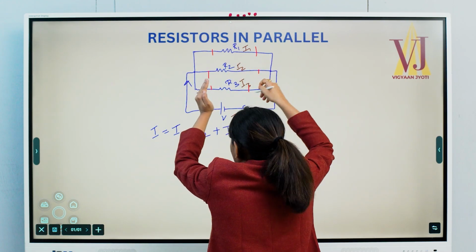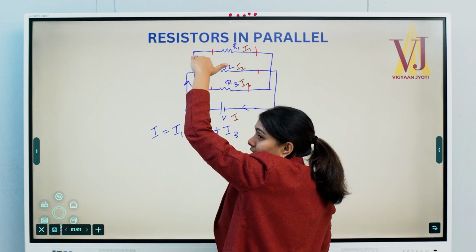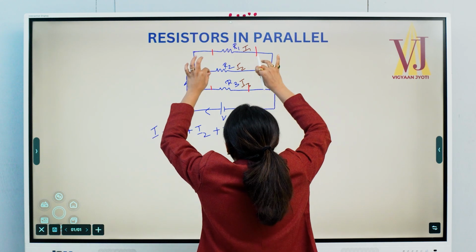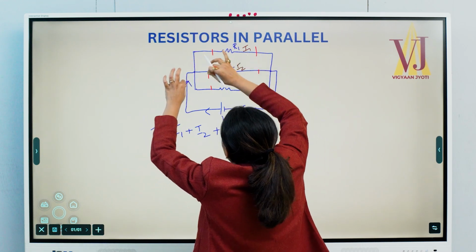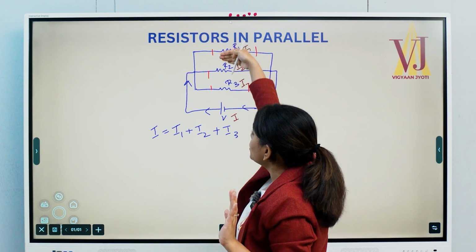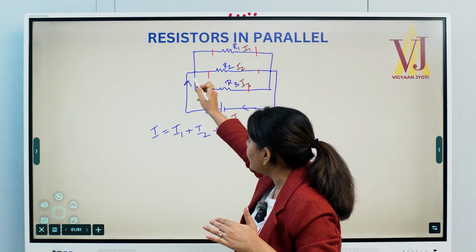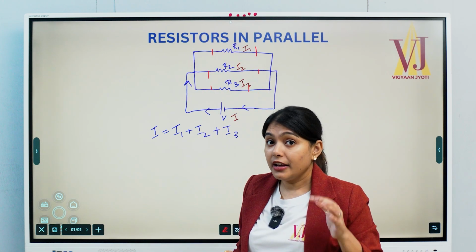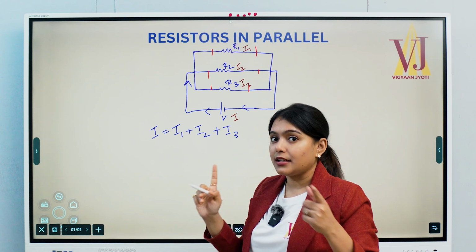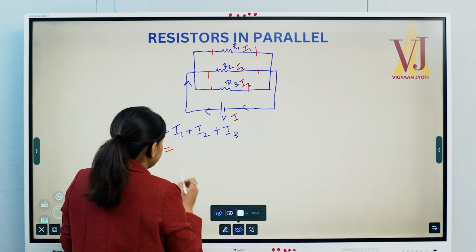All the 3 wires are having flow of current, but when we are trying to calculate the potential difference, we consider only these 2 points and see what is the electric potential across them. These paths do not meddle, because the electrons traveling here are not the same electrons traveling there, fine? So voltage is the same, current is split, hence current is different. So voltage is same.